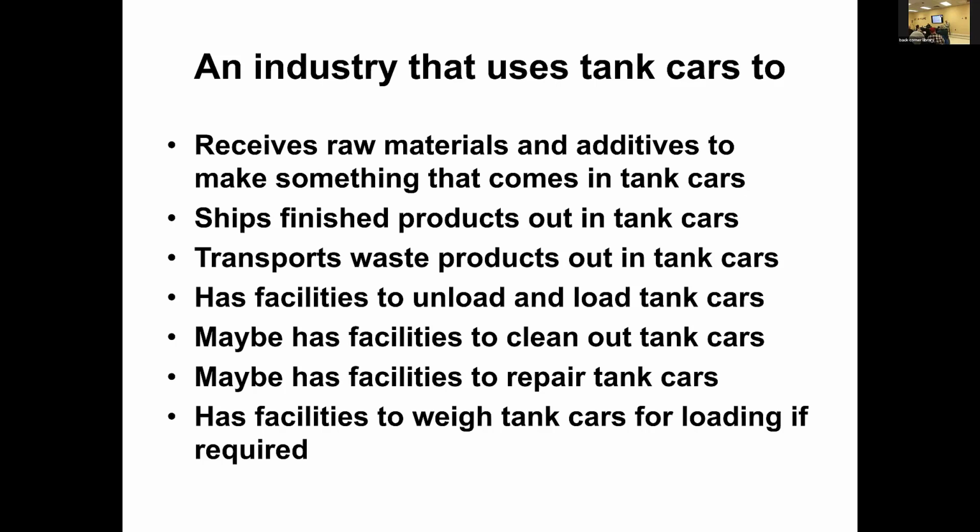So again, if we go back to our tank cars, I told you this morning that DOT 111 low pressure tank cars have bottom outlets, and they have top openings also. So how do I fill? How do I unload? That becomes important. If I bring in a pressure car, there's no bottom outlet.